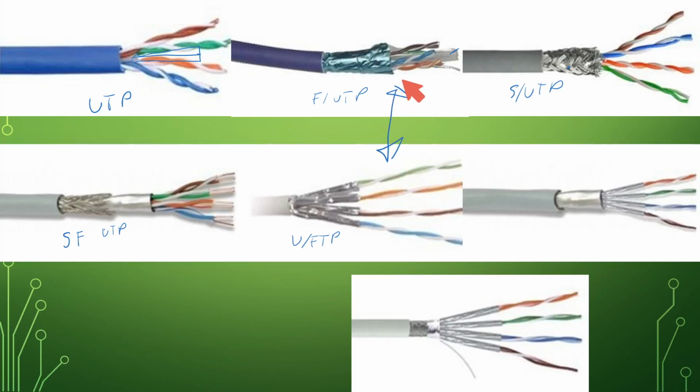What is it? Yep. The unshielded foil twisted pair, each twisted set of wires, so two wires together, have their own foil wrapped around them. Where the foiled, unshielded twisted pair, you just have one set of foil around everything. So, not a big difference, but it is a difference. In theory, this one will be better for interference from wire to wire, because each one has its own shielding, where this one, wire to wire, you can still get interference. So, a little bit of different take.